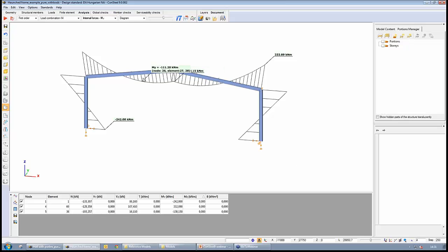We can see here the values through this graph, and we can put markers anywhere. We have tables also for the results, for the extreme values, for the selected flags values, or for all the values. So this is the basic result of this first order analysis. What we can do to see the performance of our structure for this first order analysis is run a simple cross-section check.